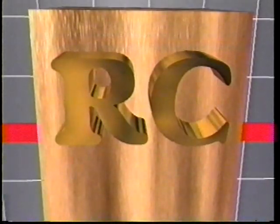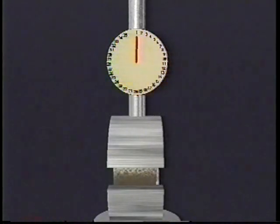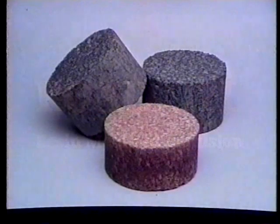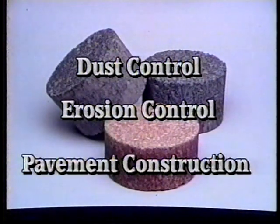It's not uncommon for road oil mix designs to exceed stability values of 10,000 pounds, or 44,500 newtons, while still maintaining the flow or elasticity characteristics standardized for hot mix asphalt pavements. Road oil resin modified emulsion clearly sets a whole new standard for bonding power, and that's important news for dust control and erosion control, as well as pavement construction.